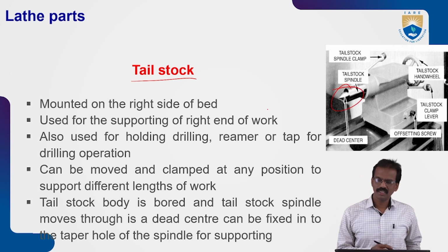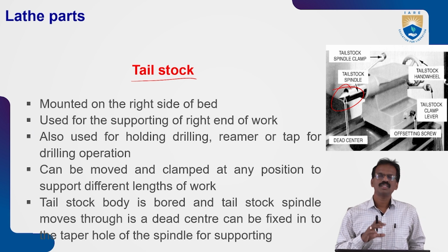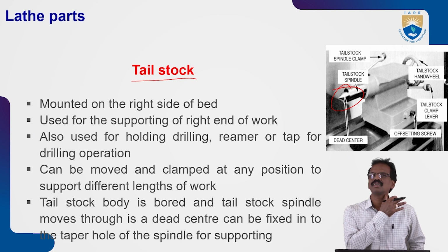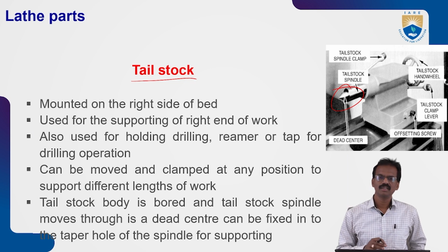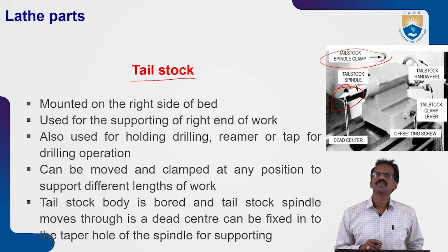This is called a dead center, which supports the workpiece to give rigidity without any shaking, for the smooth performance of different operations like cutting, thread cutting, drilling, step turning, and remaining operations. Next, this one is the tailstock spindle clamp.